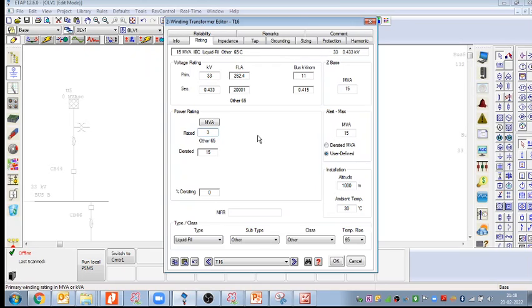Then let us see the value. 3 MVA or 3000 kVA. If we put 3 MVA, the primary FLA is 52.4, and that is very less. The secondary current is the main concern, it is 4000 ampere. I think a 4000 ampere circuit breaker is available in the market, that we can purchase from the vendor. Few manufacturers make the 4000 ampere rating, right or not?